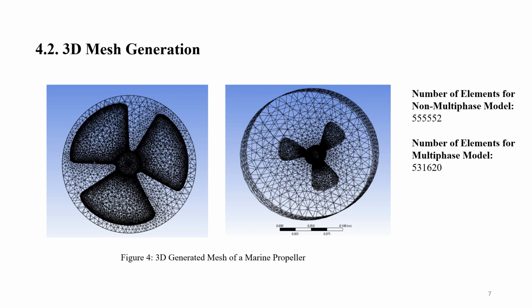Considering that the simulation involves a multiphase flow where multiple fluid phases coexist, two distinct element sizes have been defined in the mesh. The choice of different element sizes allows for a tailored approach to accurately capture the characteristics of both the rotation domain and the propeller.